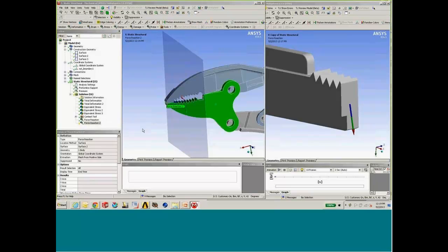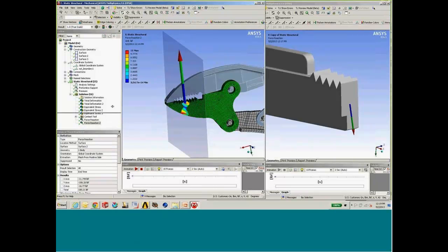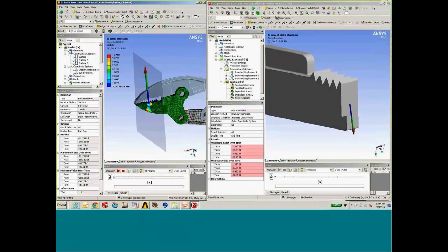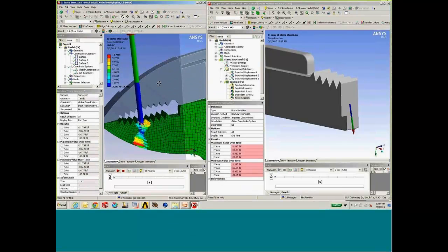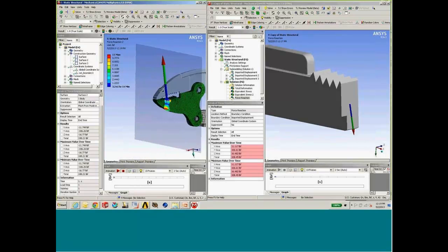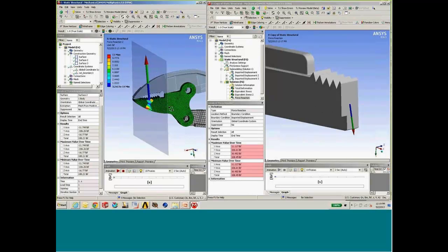If we right-click and evaluate that, we can take a look at that force response. Drag it over here so we can compare now. In our global model, you get a nice pictorial distribution of the forces along that edge for that face. You get the total vector. In this case, it's equal and opposite to what I was showing on the submodel because of the side that I picked. But when we look at the total force, or the SRSS of those forces, we can see that the maximum value is 108.21, which is pretty close to 108.45. So I think we're within some computational error there.